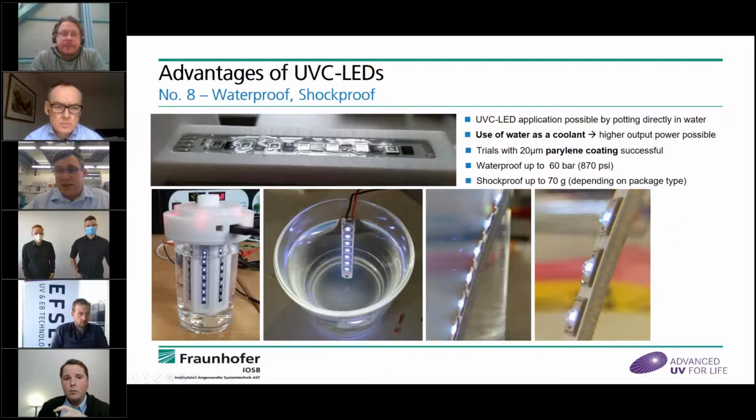As you can see, we have here an LED strip on an aluminum PCB with a parylene coating. You have to mask out, of course, the LED lens, because parylene is intransparent in UVC. But you can get the optimum cooling effect like this, for instance, for water disinfection.